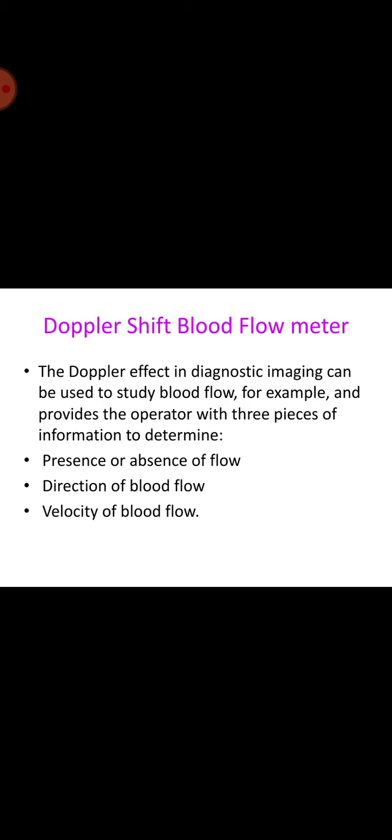So this difference in frequency, that is F plus Fd or F minus Fd, depending upon the direction of flow, the frequency will change, and the Doppler component Fd is directly proportional to the velocity of flowing blood. A fraction of the transmitted ultrasonic energy reaches the second transducer directly, with the frequency being unchanged. After amplification of the composite signal, the Doppler frequency can be obtained at the output of the detector as a difference between the direct and the scattered signal components.